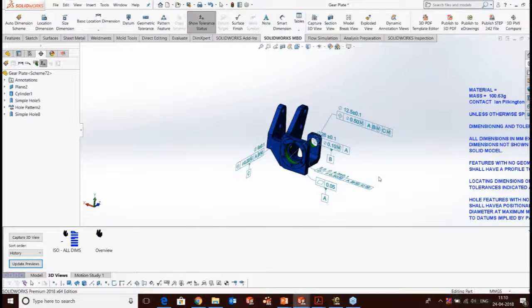So this is simple inside SolidWorks, and this is similar to the feature manager tree. We can just change the tree display to the annotation based. The importance of this tree is that whenever I select any datum or any feature or any dimension for that matter, it will cross highlight. This will help me understand much better what the design is and how the design is coming together, and I can make any changes pertaining to the designs.